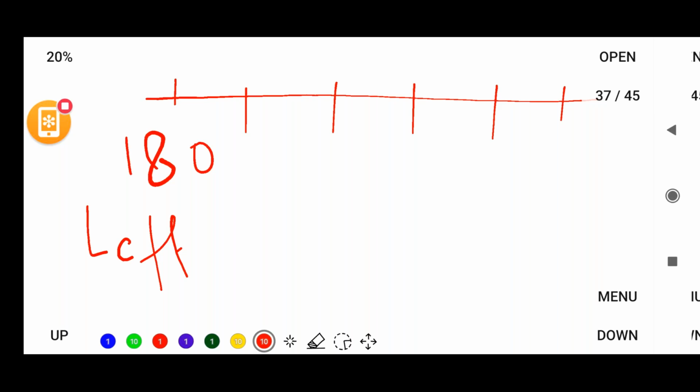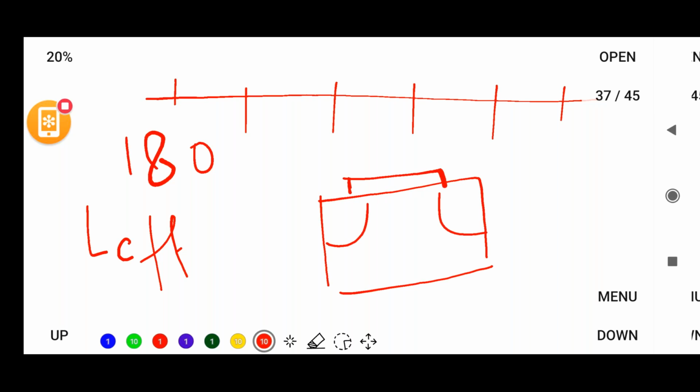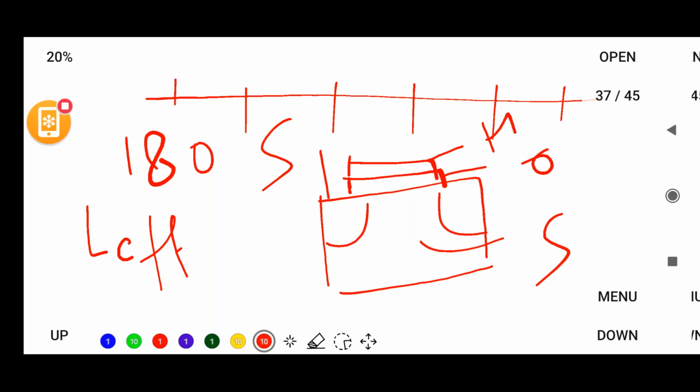Let me explain what the channel is and where it is. Suppose this is your MOS transistor, with a diffusion, an oxide layer, the SiO2 layer, and on the top layer a metal layer. So this is a metal oxide semiconductor. Between the source and drain, there is one more terminal, the gate.